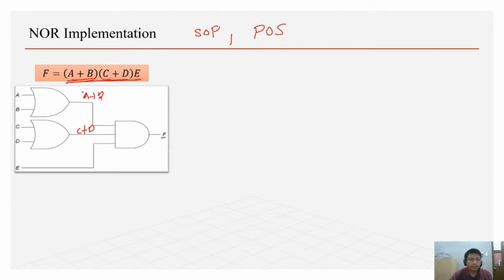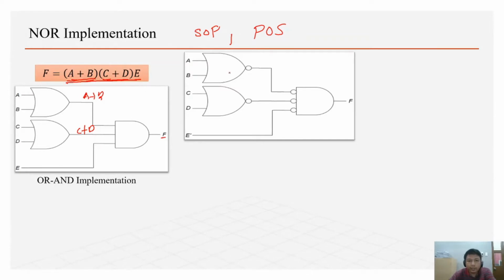So having F equal to A plus B, and then to C, D, and then to E. Okay, the rules on the NAND gate will be applied also in our NOR gate. So we can have a bubble here at the output and a bubble. So again, double negation, this will cancel out. A bubble here and a bubble here, they will be cancelled. And we have here a prime and a bubble, they will be cancelled.